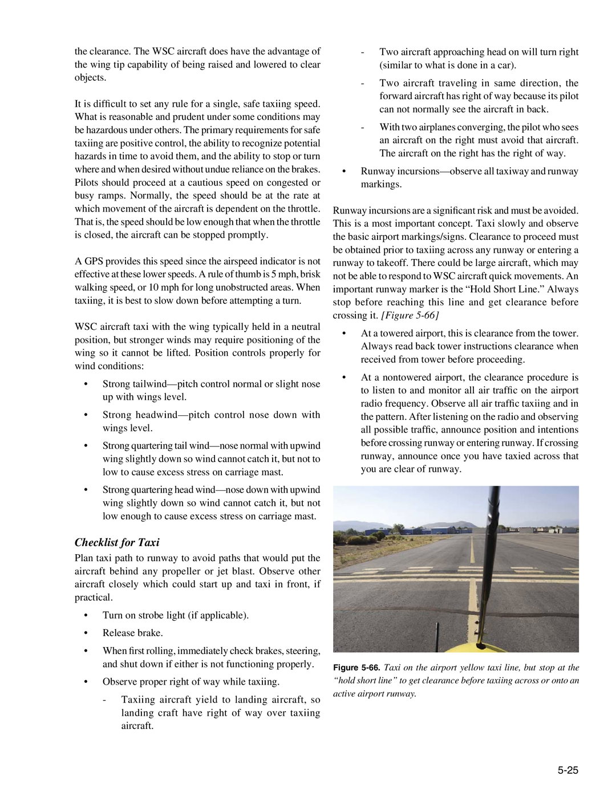It is difficult to set any rule for a single, safe taxiing speed. What is reasonable and prudent under some conditions may be hazardous under others. The primary requirements for safe taxiing are positive control, the ability to recognize potential hazards in time to avoid them, and the ability to stop or turn where and when desired without undue reliance on the brakes.